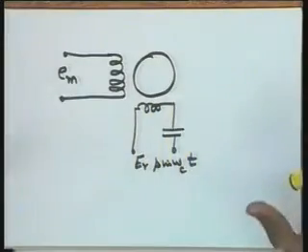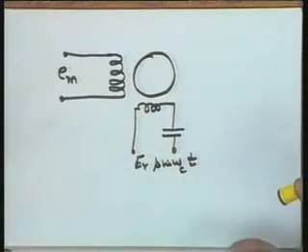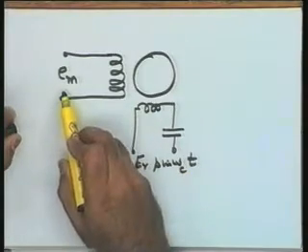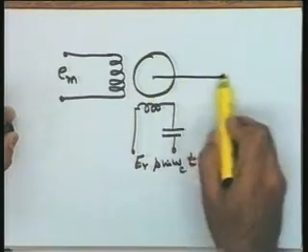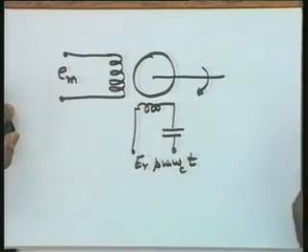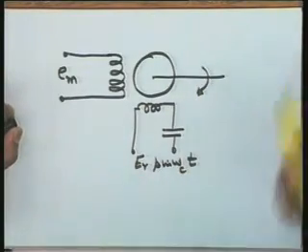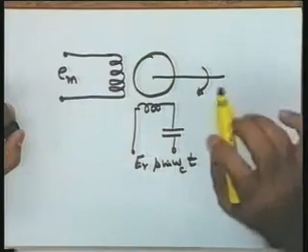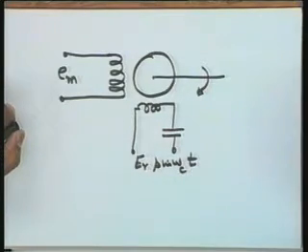But when you come and take up the transfer function of the motor, you could take the transfer function between the envelope of this signal and the speed of the motor or position of the motor, because the information in the system is carried by the envelope and not by the carrier.